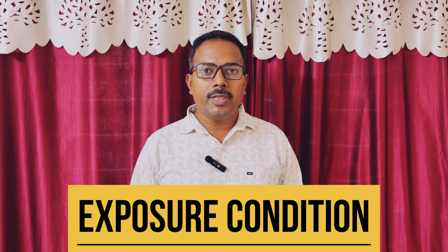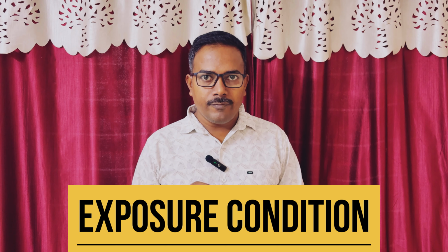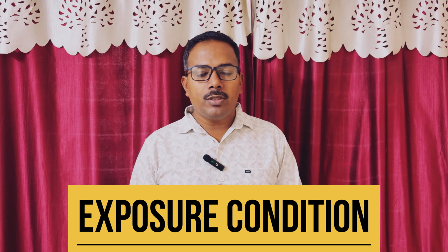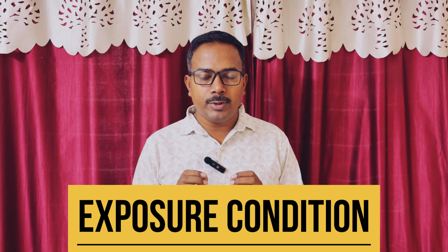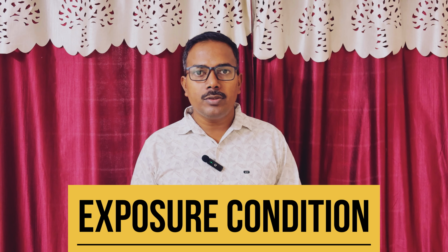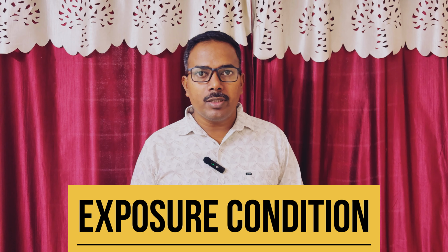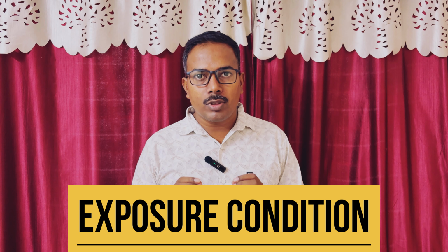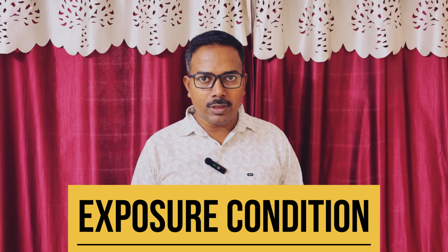Our next video topic is exposure condition, which is very important and the base of this mix design, because if you don't know how to choose the exposure conditions, how are you going to choose the minimum cement content, minimum grade of concrete and the maximum free water cement ratio? It totally depends on the exposure conditions.